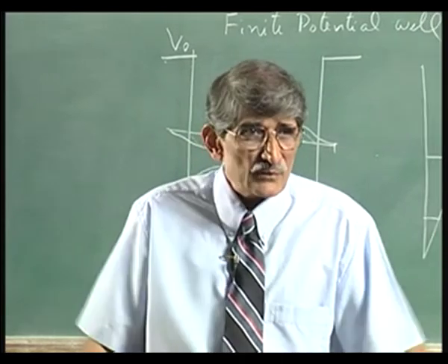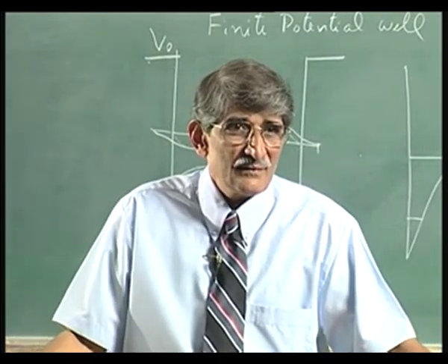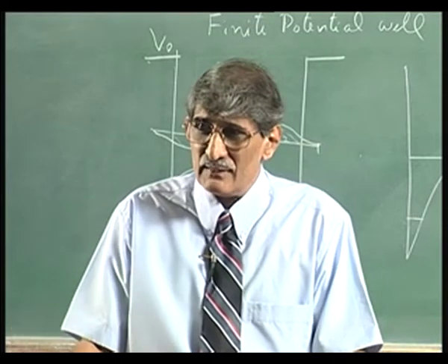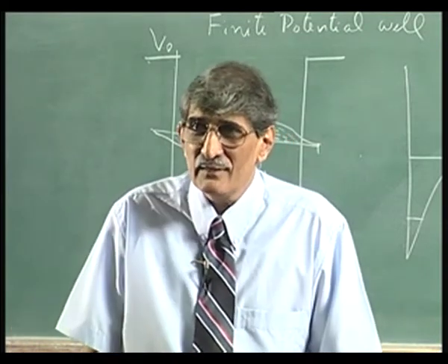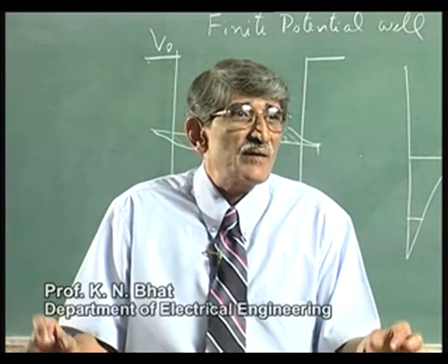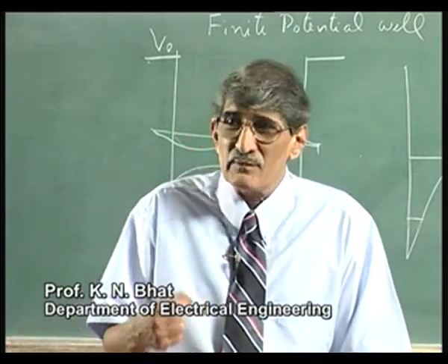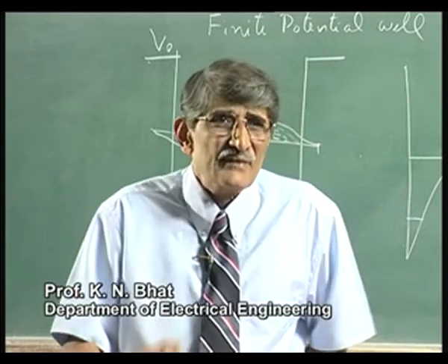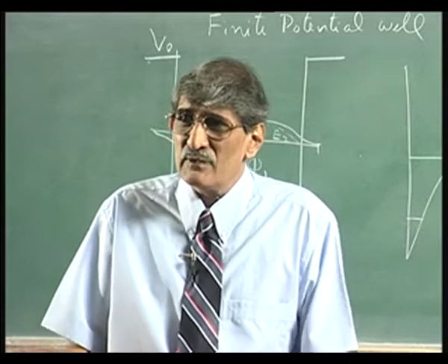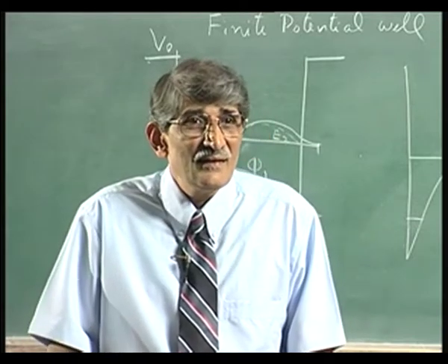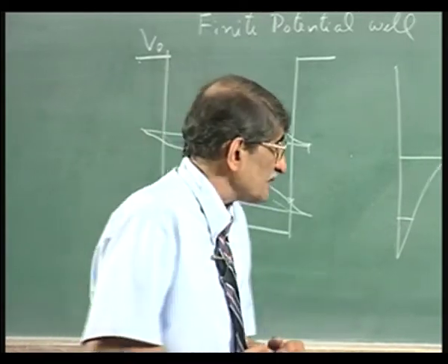Where? In the source and drain regions. There are two things, source and drain regions and the gate region. Gate region, of course, you would like the barrier height to be high. Drain region, where you make the ohmic contact, barrier height must not be high, it should be ohmic contact. That becomes difficult. Okay. In fact, you make that N plus there by gold germanium doping, but still all that happens in those situations is like this.